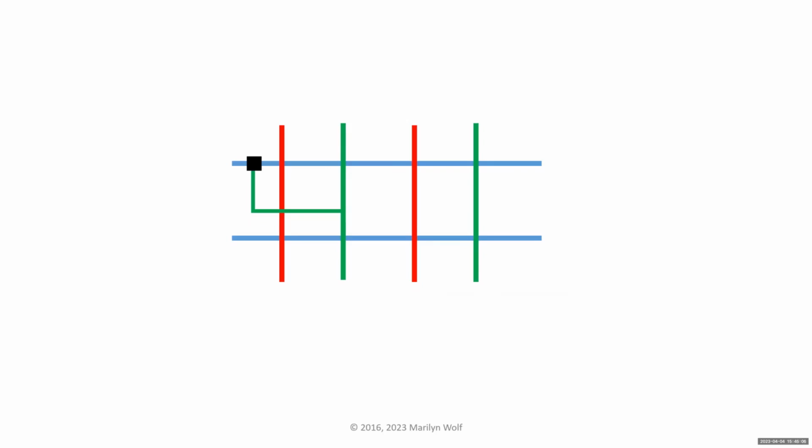Each row consists of a polysilicon line, that's the gate material, and a diffusion line running vertically, okay? Now, on the left-hand side, you'll see that there is an extra green wire that goes up to this black dot. The black dot is the via that connects that diffusion wire to the blue wire, which is the output of this gate.